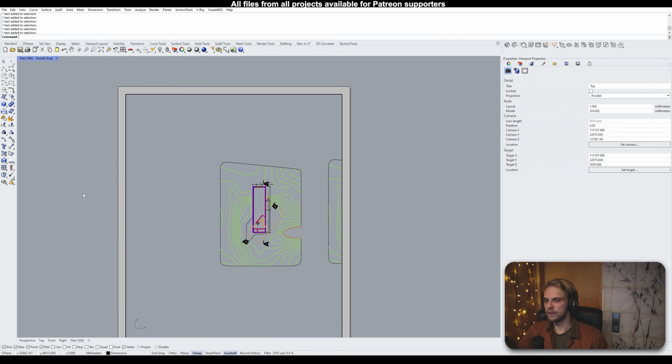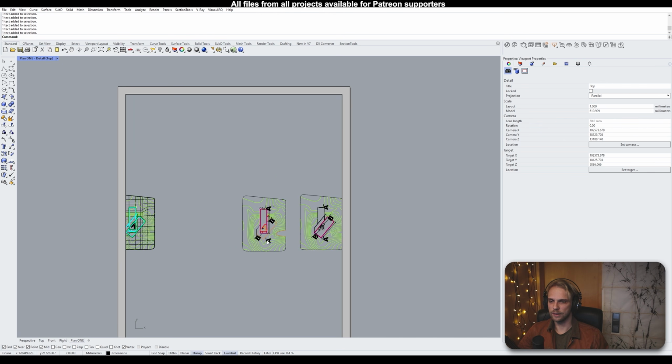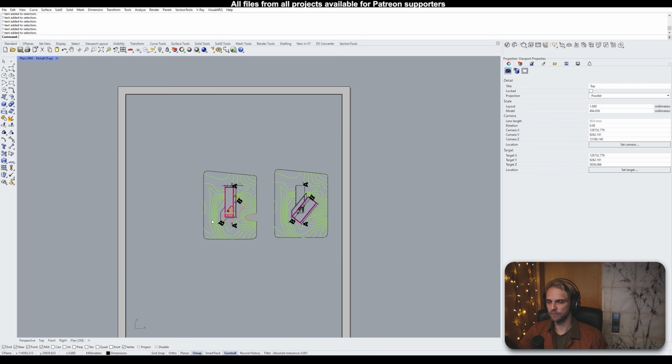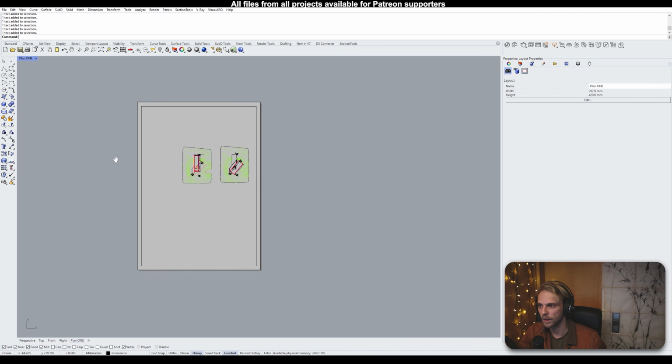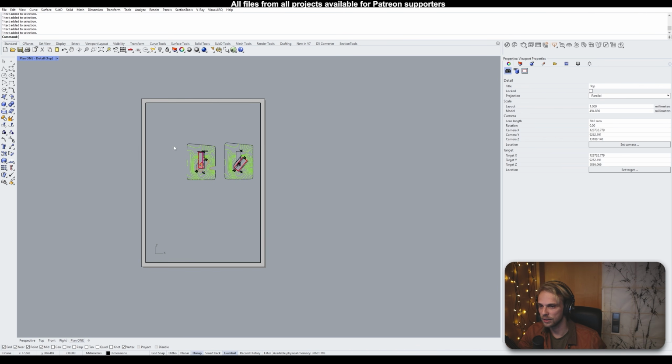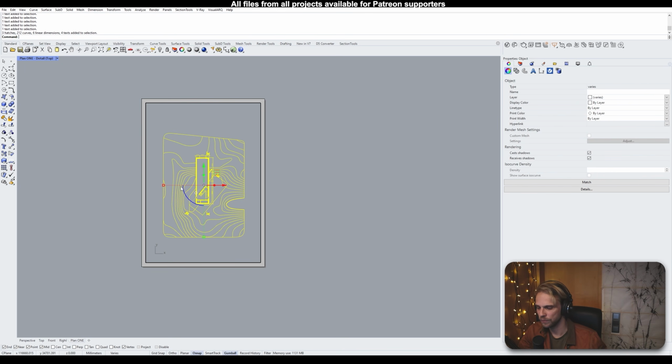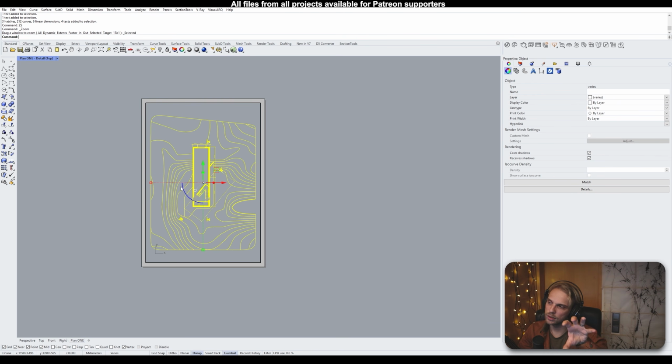How do we make this drawing right here, first of all, centered? Well, first of all, how do you even zoom in? You double click inside of the sheet, inside of the detail. When you double click, you can position the detail as you want. And how do you center it? Well, you select the geometry that you want to center, in this case the whole drawing here, and you type in ZS. Hit enter, so it zooms and locks the camera onto the geometry that you want to center here.